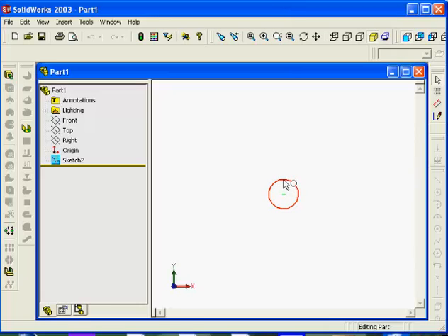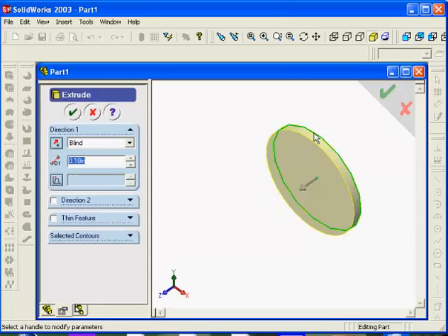So extruding a circle will make a cylinder. So we go up over to the feature menu and we go to Extruded Boss. Notice that it changes to an isometric view, and we can see what it's trying to do for us. All right. So here I've got some choices, and right now we're going to use blind as our starting point for the extrusion, which really means that it starts at one end.